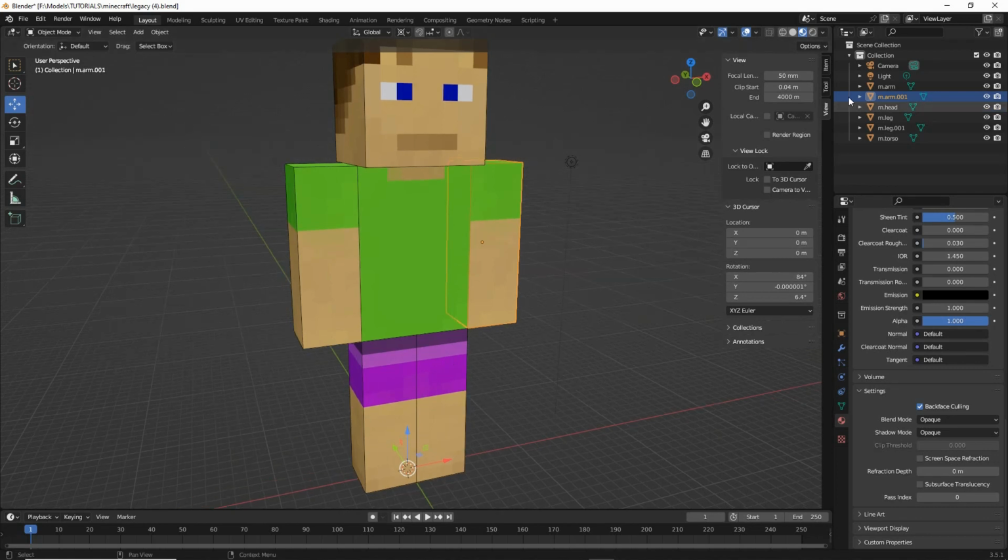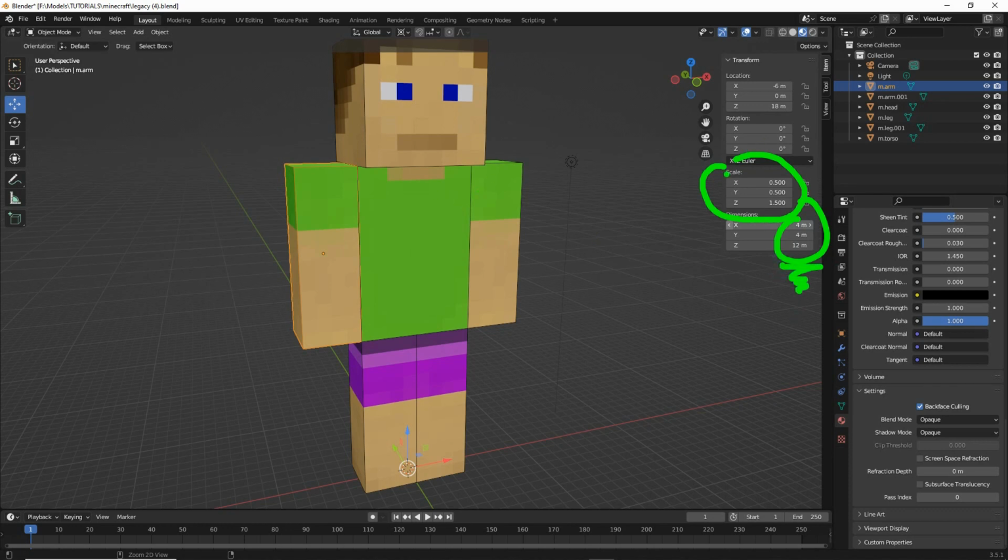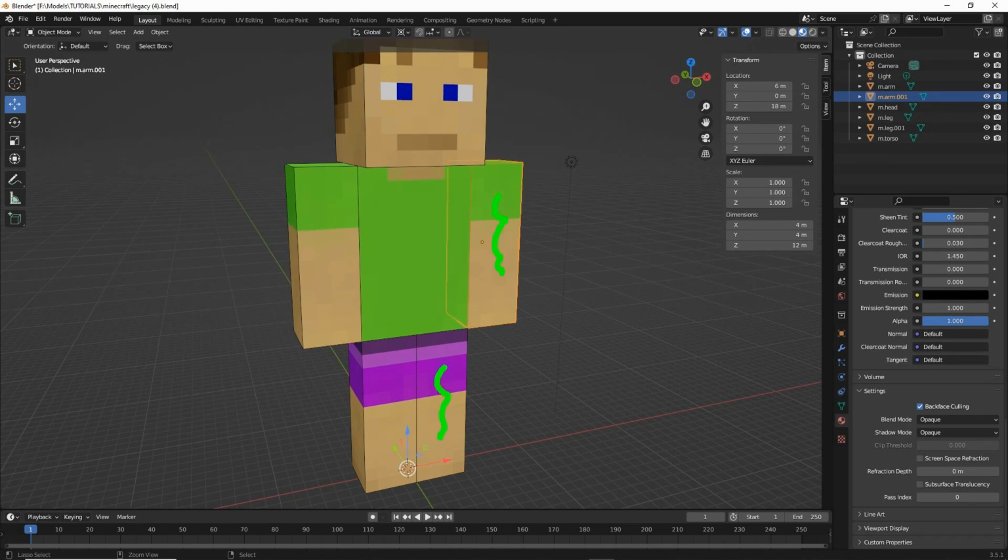So let's just go to Item, double check something. So we're checking object size, but we've also now got scale because we changed the size of our objects. We want to fix this now before we go any further. So we want scale XYZ, we want all of that to be 1. So we can see that on the side that we fixed, because it was inside out, they are already 1. So we want to do that to all the objects.